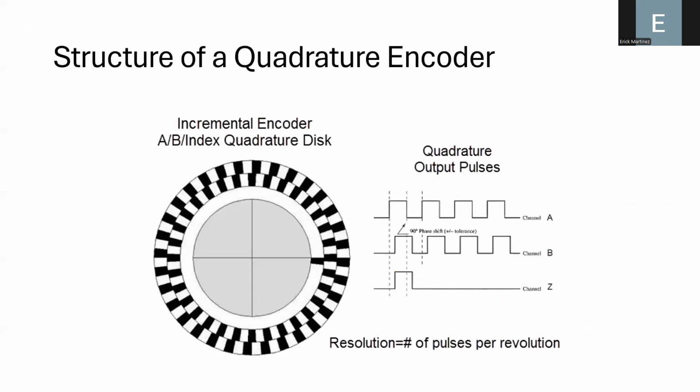Okay. And also there are other types of encoders that are called quadrature encoders, which basically consist of two disks. We have one outer circle and one inner circle, and the holes are misaligned by 90 degrees, more or less. And the idea is that we want to produce two different signals. That is, we will be using two different infrared sensors.